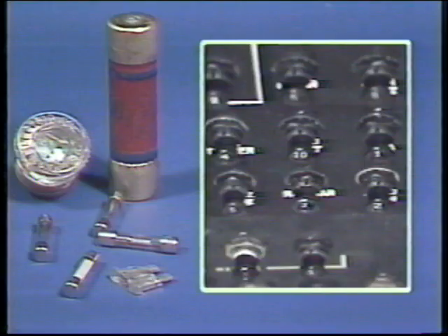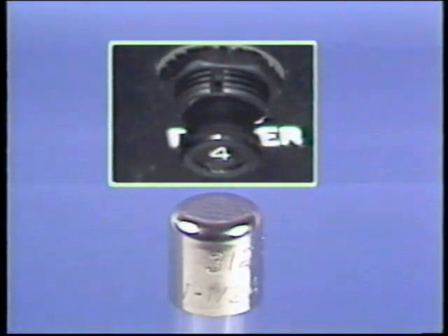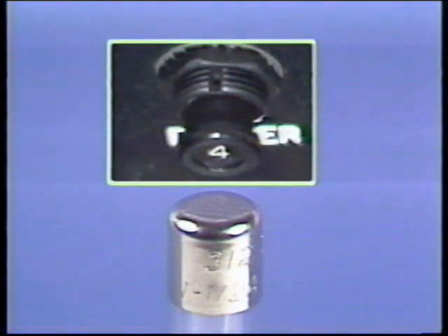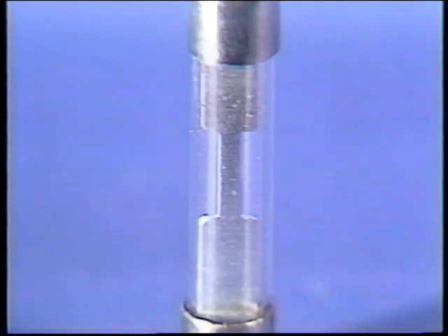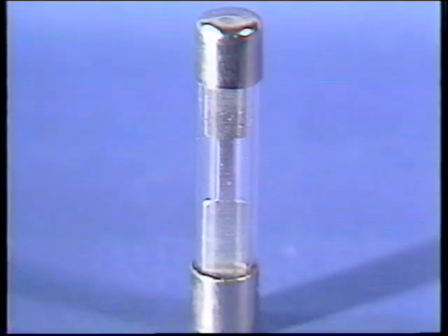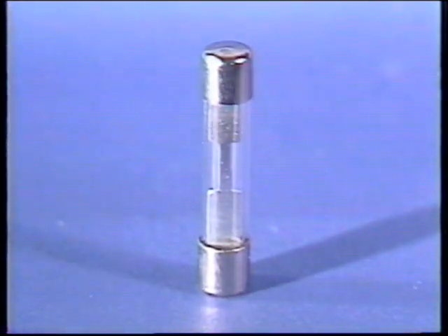Electrical circuits must be protected from too much current flow to prevent overloading the wiring and burning it out. Not only is an overload damaging to the wiring, but it is also a fire hazard. Circuit protective devices are designed to open the circuit and interrupt the current flow if the current flow exceeds specified limits. A fuse is made of a metal alloy strip with a low melting point, usually enclosed in a glass case with contacts on the ends.